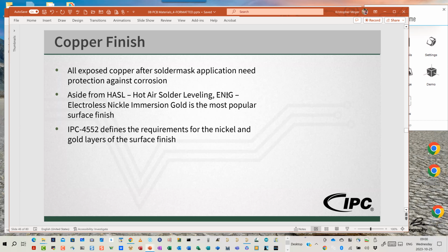It was, I want to say, at the time, this is like the 2008, 2010 time frame, about a 10 to 15% cost adder to the board to go to that process. Maybe 5 to 10% for those two, and like a 10 to 15% cost adder to do the ENIG at the time. So whatever you would have paid with HASL, you pay about 10% more to do ENIG and about 5% more to do immersion silver, immersion tin. Again, old data.